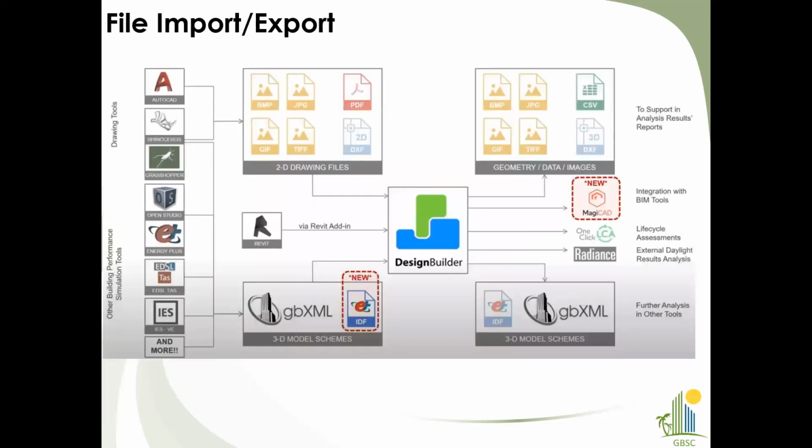One of the most important features for us right now is that, because of the integration of design and multidisciplinary teams working across nations, we receive multiple format files. For example, we may receive a Revit file developed by the design or BIM team. DesignBuilder has a dedicated plugin which we can install within Revit, and that plugin simplifies the model and converts the BIM model to a BEM model, from building information modeling to building energy modeling. It takes out only the information required for the environmental analysis, exports that file, we import it within DesignBuilder, and then we can post process it there.